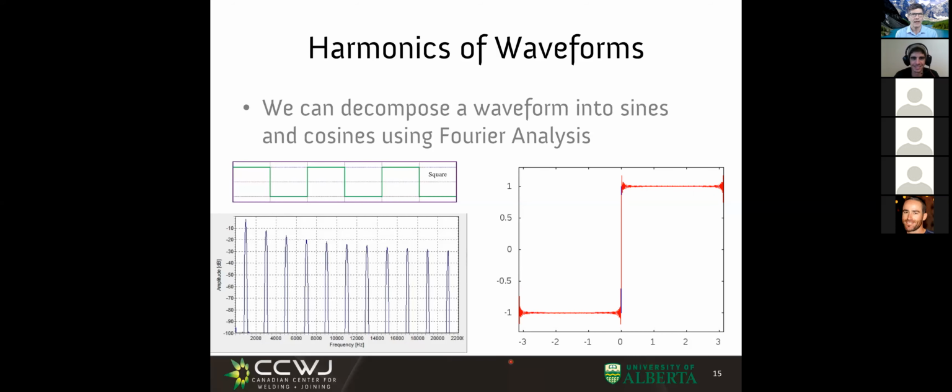If you try to do AC TIG with a transformer type of machine, it's likely not to work very well because as we approach zero gradually, the arc just extinguishes and doesn't start again. So you have to go very quickly through zero. Isn't this amazing? Like how things come together. 6010, 6011, TIG, square waveforms, transformer power sources. We have this little bit of understanding and we can explain so much and understand so much.